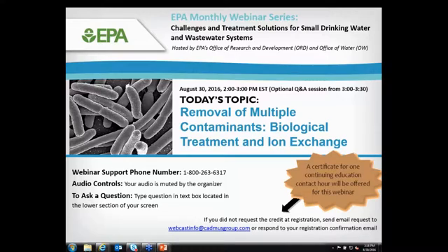Then, using nitrate as an indicator, after about 12 hours we would find nitrate removals back up to about 80% of what we'd observed before backwash, and it took a full good 24 hours for nitrate concentrations to get back to normal. What this points to once again is that at this stage in the game, when you install a biological treatment process, there potentially needs to be some type of backup treatment downstream.